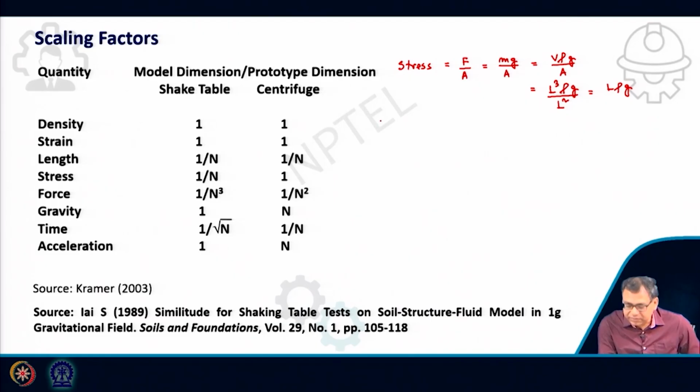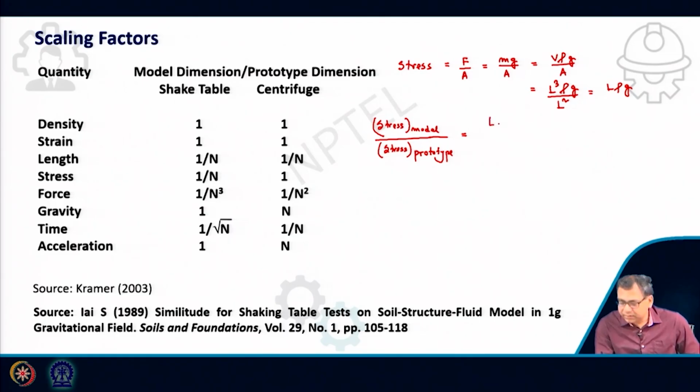Clear? Now the stress for the model divided by the stress for the prototype will be equal to L rho g of the model divided by L rho g of the prototype.